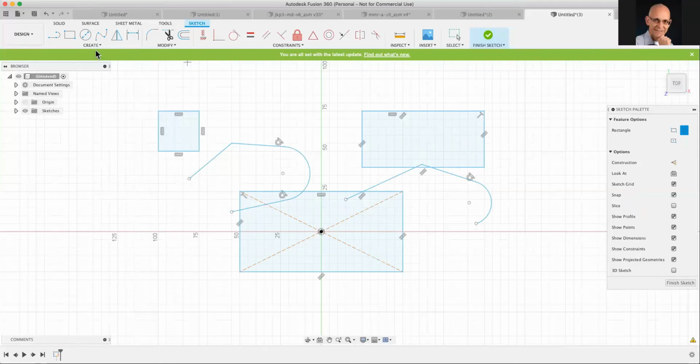So if you want to verify what sketch plane you're on here, you just look up to the cube up there, and that shows you that you're on the what, X, Y? In this case, yeah, I'm on the X, Y, which is from a top view. So if you had projected something, what's going to happen? Well, if I projected something parallel to top, it would still look like top.